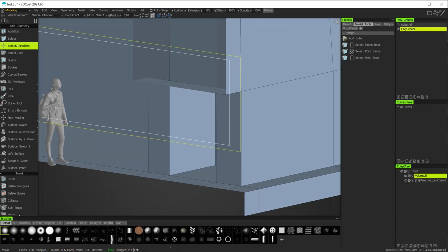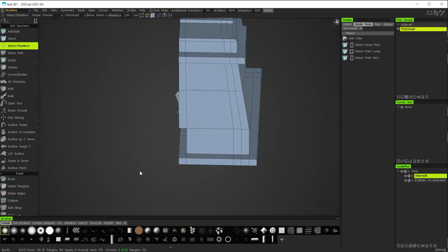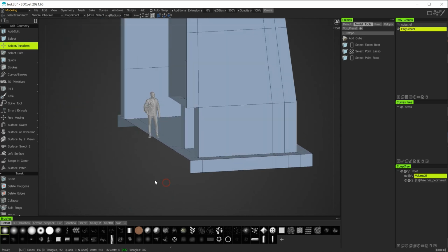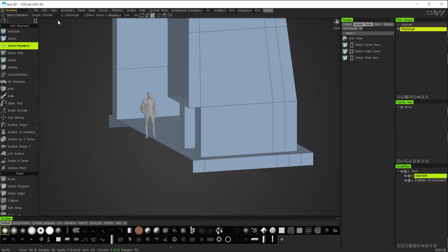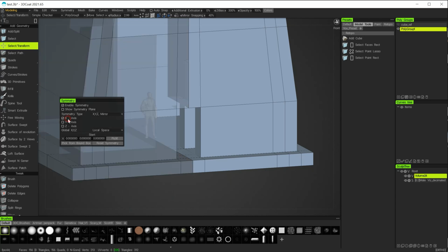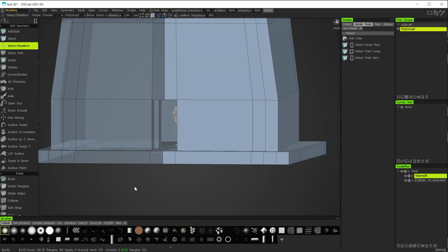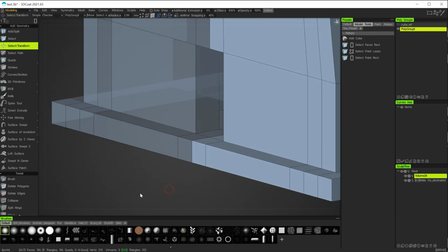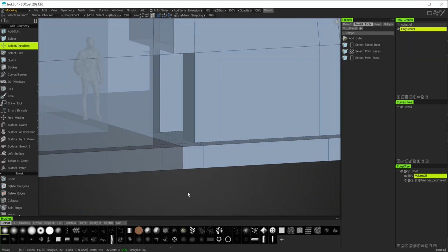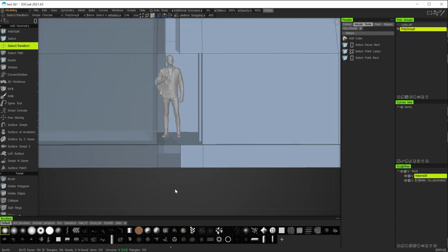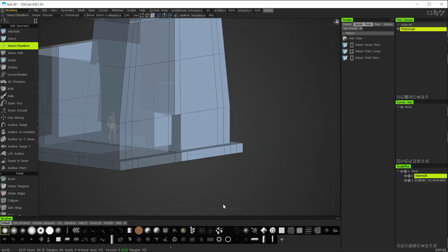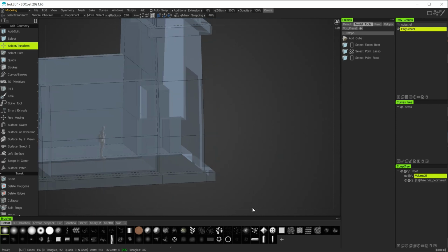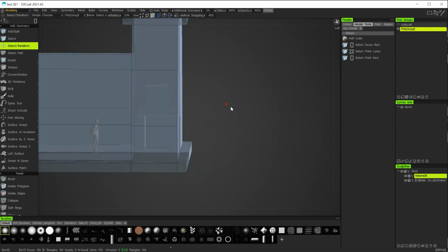So let's drop that tool again and bring back the virtual mirror on there. Oh, make sure symmetry is on. There we go. So now I've got a doorway with an internal area inside that main front wall. And you can see that sort of cavity space there.